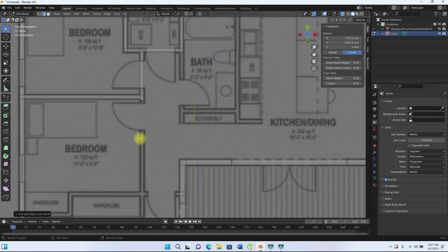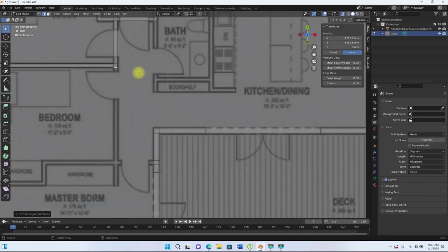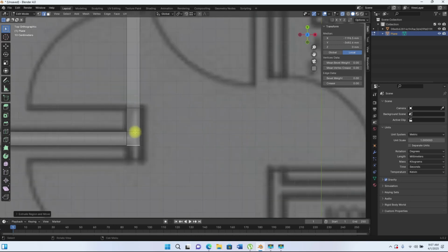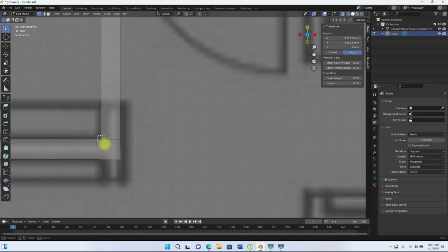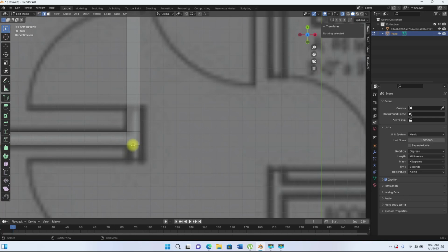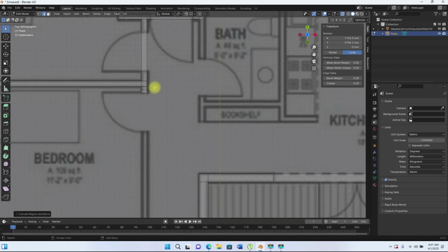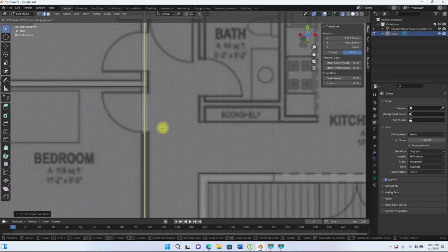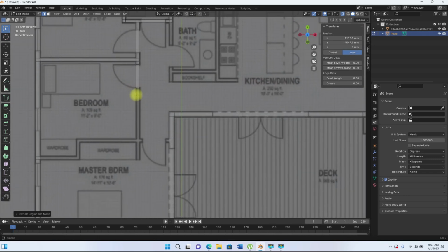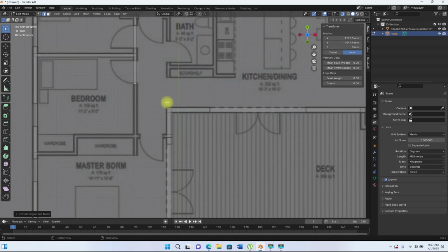And then I can continue my extrusion because it's still the same guy. I'm going to merge this. Let me just go into one, merge this, M center, select this, M center. So go back to 2 for these points, E Y, so extrude this here. So this is basically how you will continue extruding this till you are fine.